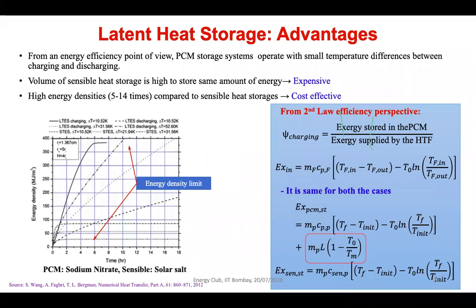So now, what are the advantages? First, as I have told you, it has a very high energy density compared to sensible heat. Also, if we go through the second law efficiency in thermodynamics, we can say that the second law efficiency will be higher in the case of latent heat thermal energy storage. However, the drawback is that it is expensive compared to sensible heat, and it needs special attention while selecting the material, which I will now describe briefly.